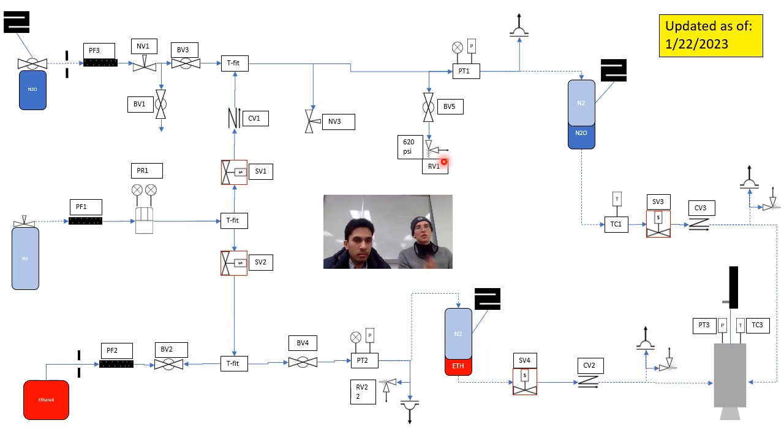However, if you close BV3 and then the goal is to take off nitrous oxide, repressurize it with nitrogen, and then put it back on, a potential concern is that you might open this section of the feed lines to atmosphere, and then when you put the nitrous oxide back in, you have got liquid nitrous oxide mixing with atmosphere before it goes into the feed system, which potentially could cause problems.